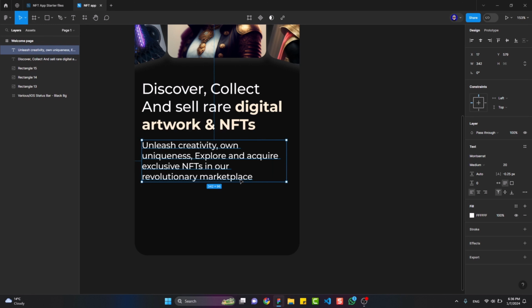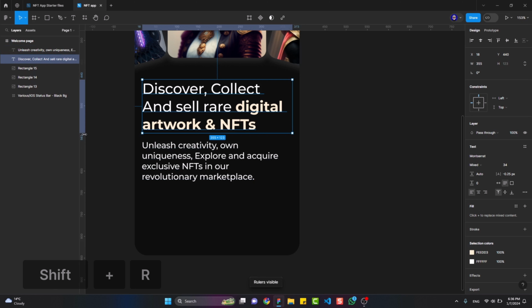If you want to add a guide for yourself to see where you should place them, you have two options. First, to add grid to your frame or add some rulers to your project. Because right now we don't have many things on our pages, I prefer to stick to rulers because it's cleaner and easier to do for now. You can add rulers by holding Shift and R to make these appear. Then grab them and bring them to our pages.